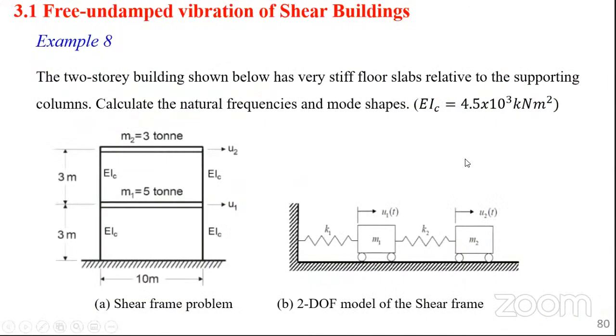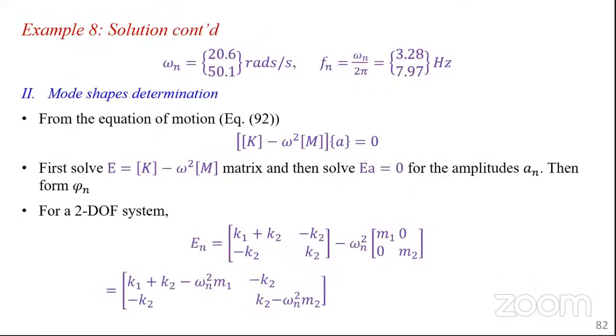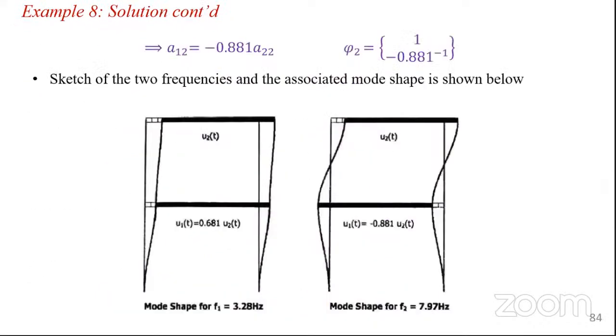when we are solving this problem, if you recall, in brief, what he was saying is that every structure has got a tendency to vibrate. And there is the natural frequency at which they vibrate, of course, now that you're talking about solving the natural frequency, the structure will deform. For each vibration, it will have a different shape of deformation, what you call the mode shape. And we talked of mode shape being unitless. And we do this by normalizing. And a number of ways of normalizing or setting the maximum value to 1.